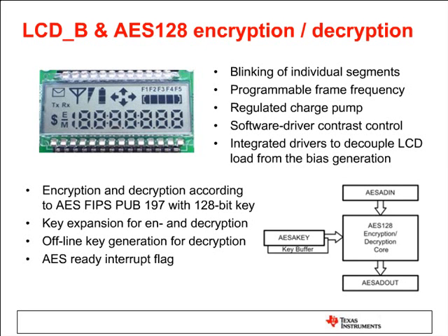Then you have the AES encryption module, which is interrupt capable, and it handles both the encryption and the decryption. And I mean, that's about it. What I like about that is that we also have a software library on the AES. If you go on www.ti.com/MSP430 and you click on the Application Notes tab, we have a software library for AES encryption. But when you look at the cycles that consumes and the cycles that it saves you, I think it's in the thousands in terms of what this hardware module can do for your application. So in terms of MIPS added, it's just a great feature to have on the device.